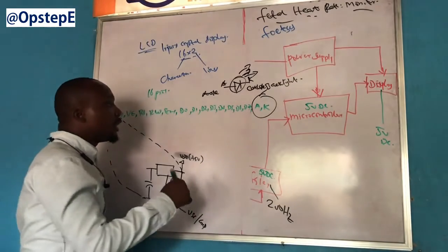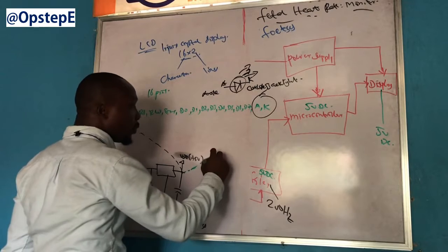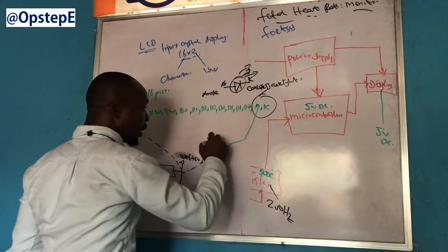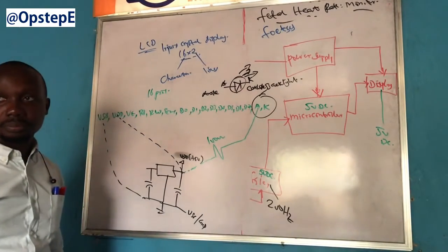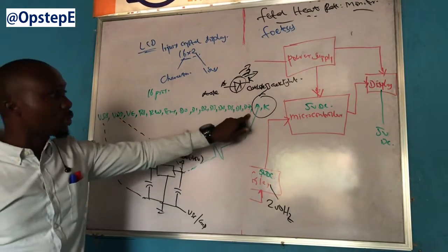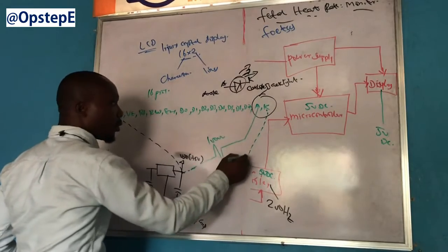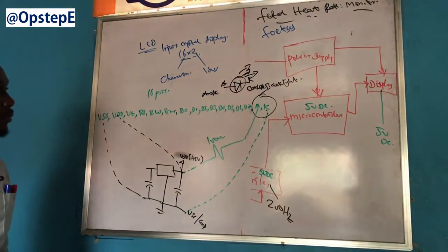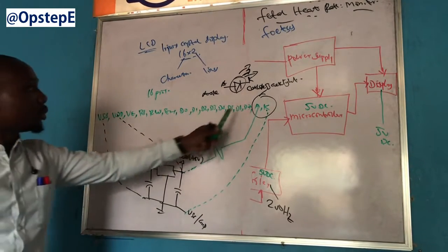So what we did was from your VDD, we had a resistor going into the anode. This is a 100 ohm resistor from your VDD connected to the anode, while the cathode came back and connected to your VSS. That was how we eliminated pins 1, 2, 3, 4.